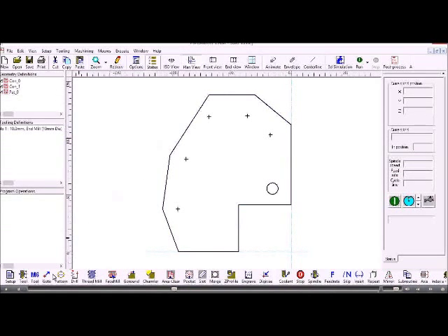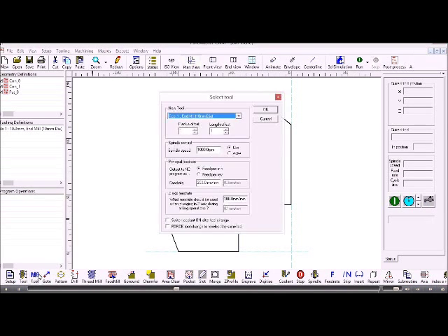The next thing we'll do is we'll use that tool. So we invoke a tool change, M6. So we choose the tool that we want to use. There's only one tool that we can pick up, which is tool number 1. The length and radius offset registers are not generally used. Again, on older controllers you might have tool number 1 invoking offset register D21 for a radius value and H51 for the length offsets register. But in most cases just calling up the tool number will set those for you.